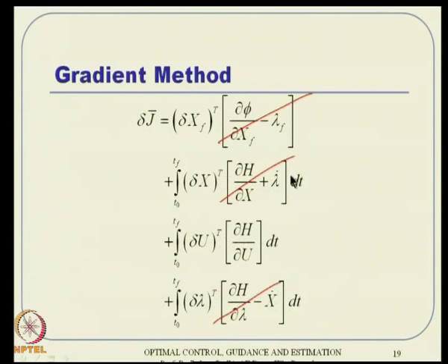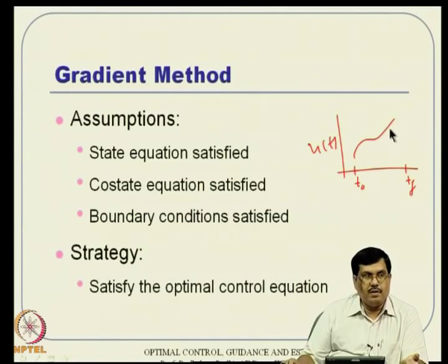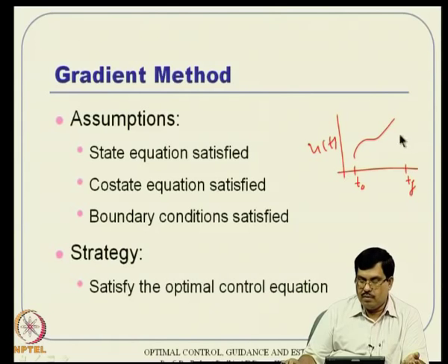You can integrate this lambda equation backward from Tf to T0, and then in one go update the control history. That's one possibility. Or, while coming back in the backward integration procedure, at every point of time you can update the control right there, and then integrate 1 delta t backward. Then update the control there, and with the updated control integrate 1 more step backward. That kind of thing you can also implement.